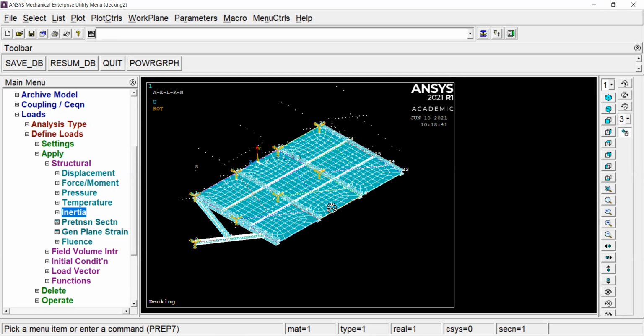And we know that pressure, because we can only apply a pressure to this thing. If we apply a point force, that won't be accurate, or we won't be able to apply a point force to a plate or a shell element. It'll start to deform the whole thing disproportionately. So we'll apply a face pressure instead, a pressure downwards. So that's our force divided by the area of that plate. This plate is 1.8 by 1.2. So that'll give us a pressure value of 2,725 pascals. You following me?